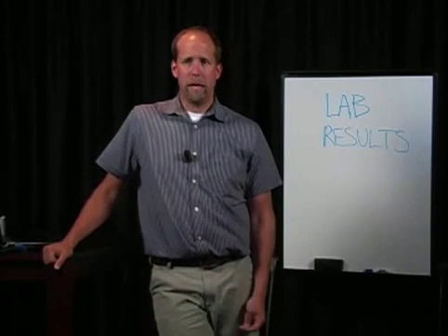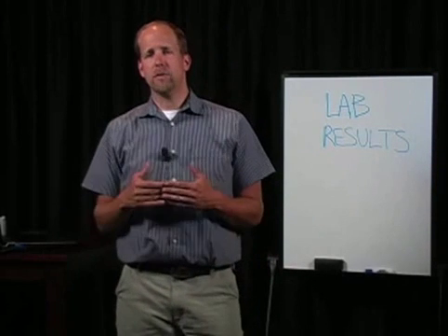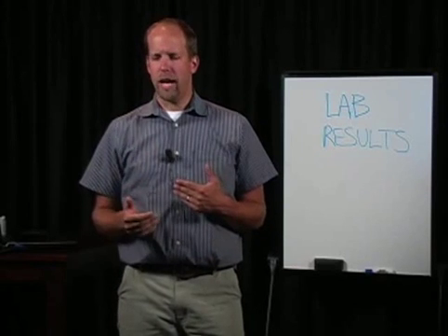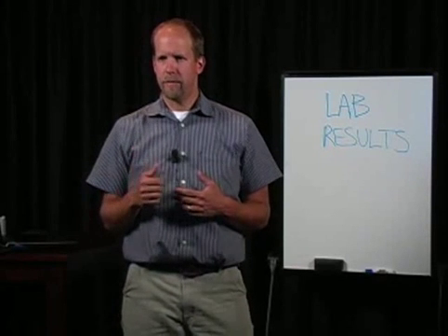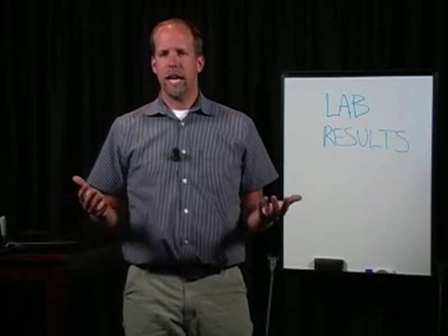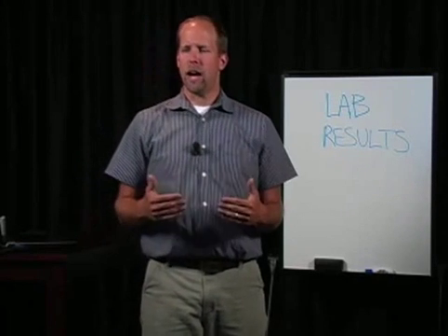Drywall may be dried in place if there's no obvious swelling and the seams are still intact. Otherwise, removal of that drywall is necessary. The wall cavity is the most difficult area to dry, and it should be ventilated if drywall is left to dry in place.